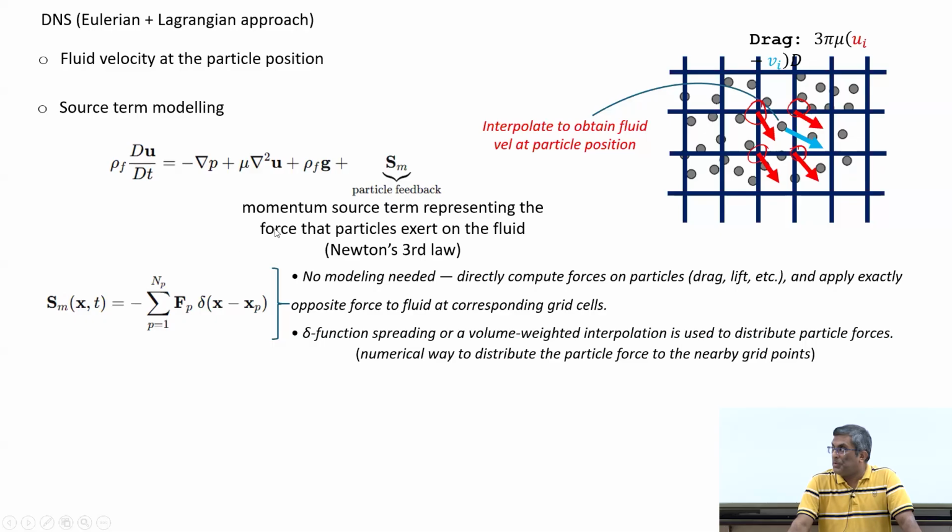But there is a difference between this term that we see here and the source term that we had derived earlier. Can anyone guess why there is a difference? How we derived the source terms earlier without considering turbulence? It was by considering the volume averaging, if you remember. So we basically volume averaged all quantities, okay, and then we got the source terms.